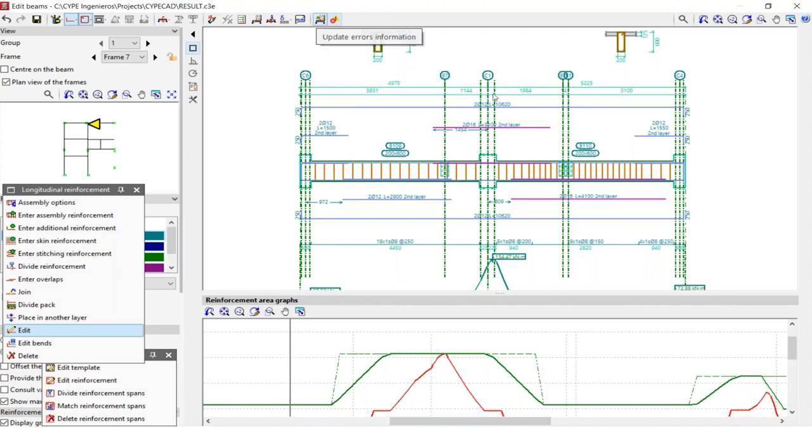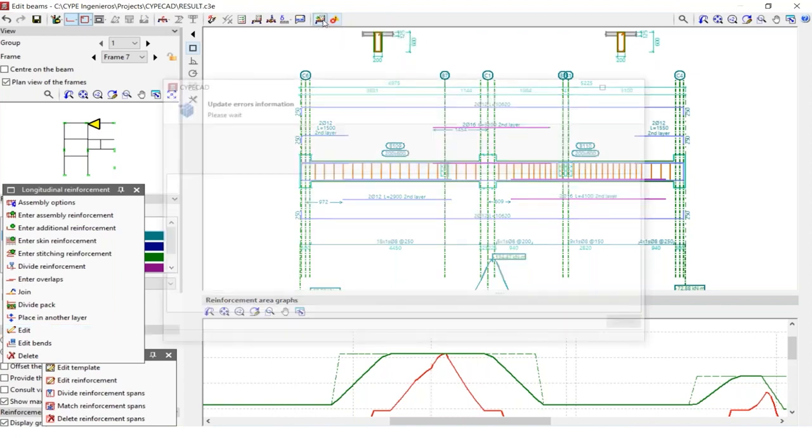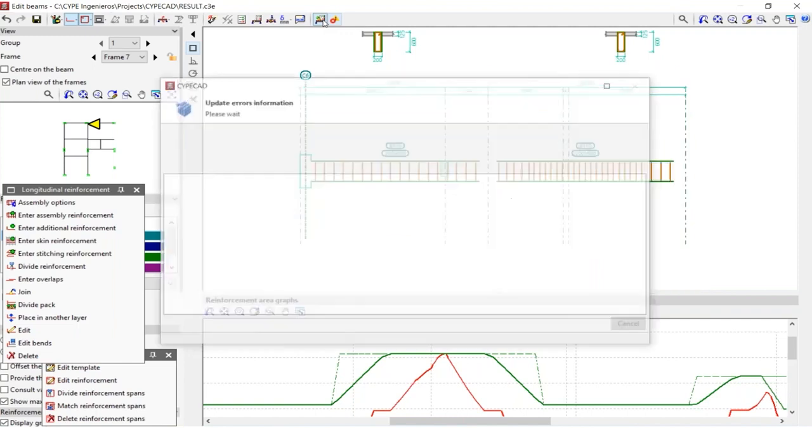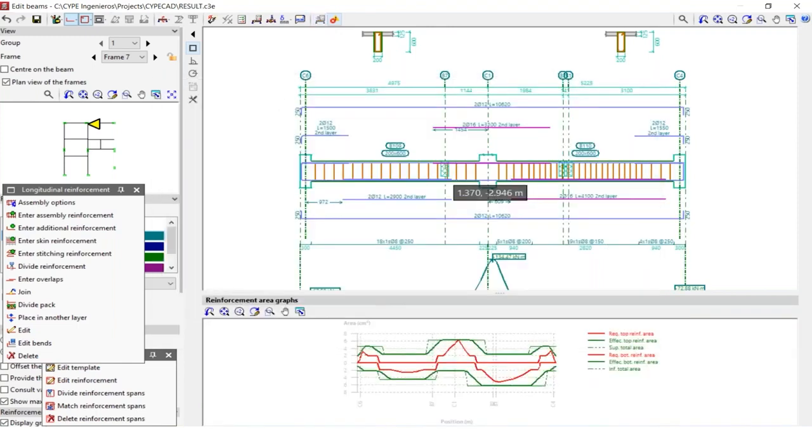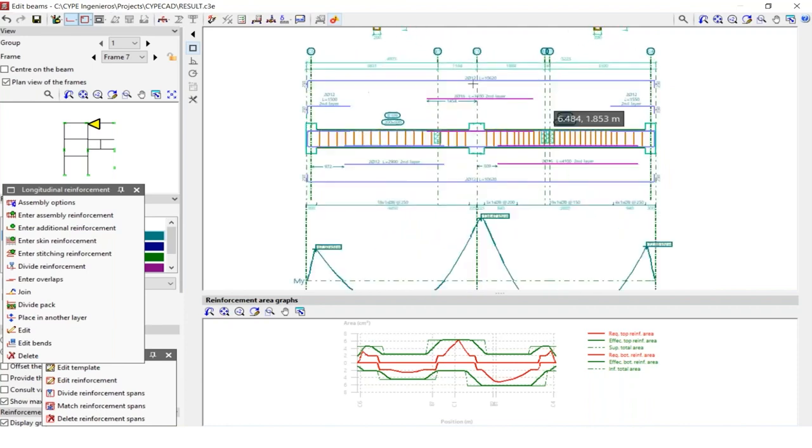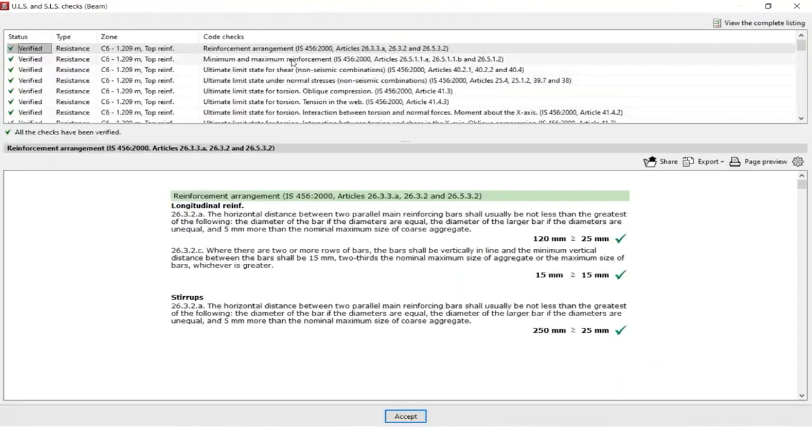And finally, if you want to make any cross check whatever you have done, whether it is okay or not, you can simply click for the codal provision checking, and the software says yes, it is possible. And like this, you can do optimization of the reinforcement also. Once again, if you want to find out the design calculation, you can find a design calculation report here.